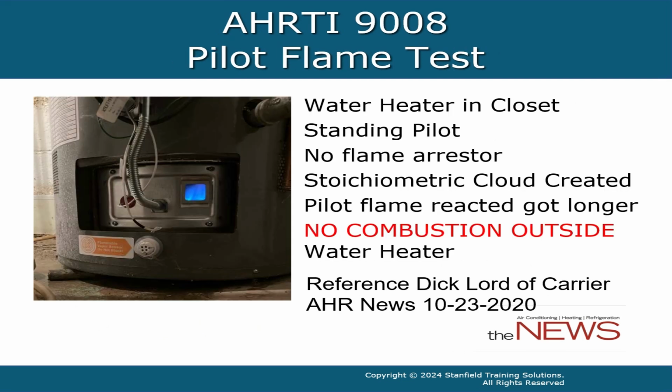Another obvious potential ignition source would be the pilot light on a gas water heater. So they took an old gas water heater, not one with a flammable vapor ignition resistant technology, and they built a stoichiometric cloud down near the base of the water heater where it pulls in its combustion air. The pilot flame did react, it got longer, but there was no combustion outside the water heater. In other words, the pilot light did not light the vapor that was accumulated at the base of the water heater. Again, my reference for this is the AHR News article on October 23, 2020.